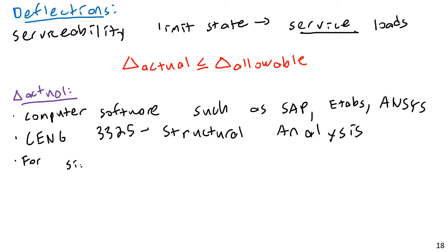For simple beams, you can use the table, and that is table 3-23, which has some pre-calculated shear and bending moment equations, essentially. If you have this in front of you, for each of these you'll have maximum shears and also shear functions. You'll have reactions, and you'll have moment and also deflections, at least for many of them. So you can use that, and again, at least for the 15th edition of the manual, that is found on page 3-208.